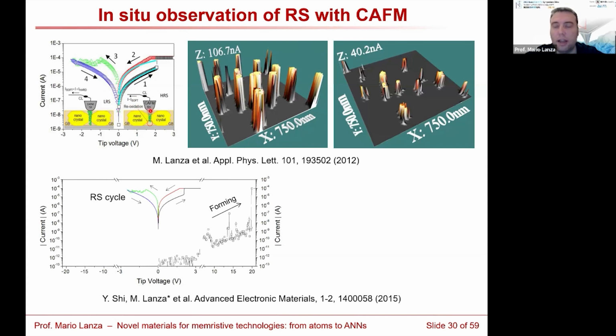Later, by making some Kelvin probe force microscope measurements, we also observed that this is related to a higher density of defects at the grain boundaries. And by making current maps with different voltages, we could observe statistically the presence of filaments with different diameter and different current. I have to emphasize that this is a non-standard experiment that cannot be done with most conductive